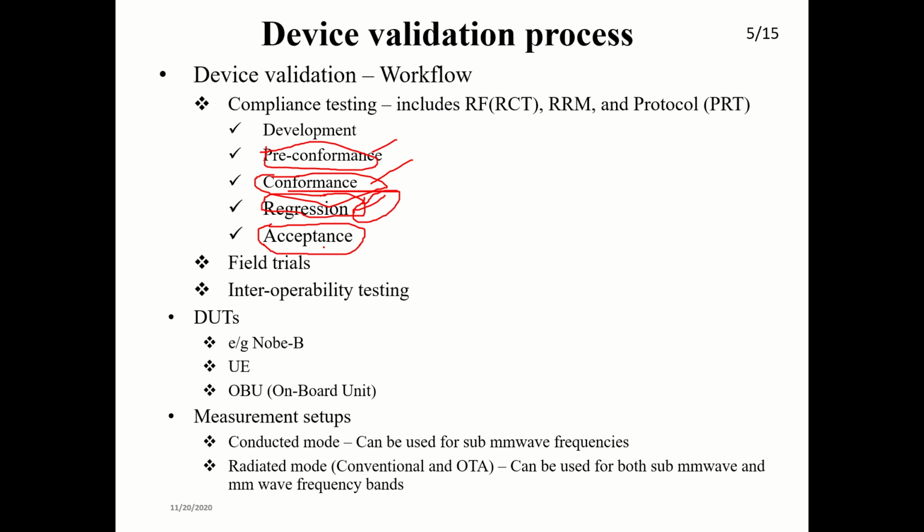Though they do several measurements, only after that do they formulate the channel models, as we discussed in the last presentation. They will measure each and every scenario, for example buildings, multi-storey buildings, trees, mirrors, and concrete walls. Then, based on the data available, they formulate the models, like the Friis transmission formula, Rayleigh fading or Rician fading. Several fading methods are available. We also discussed some more models last time from New York University.